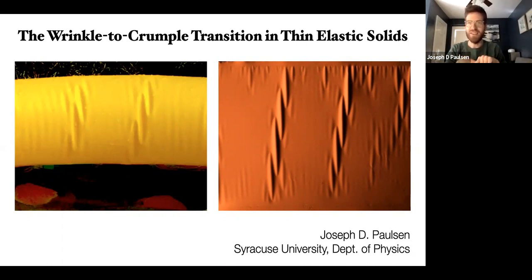And on the right, you see a photo from my lab, which is an extremely thin polymer film, just about 50 nanometers thick, but about 3 millimeters wide in its lateral dimension. And the thing that I hope is striking you is that there's this fascinating buckling pattern that you see in the left picture and also mirrored on the right picture, where these diamond-shaped, discrete buckling patterns are lining up in chains.